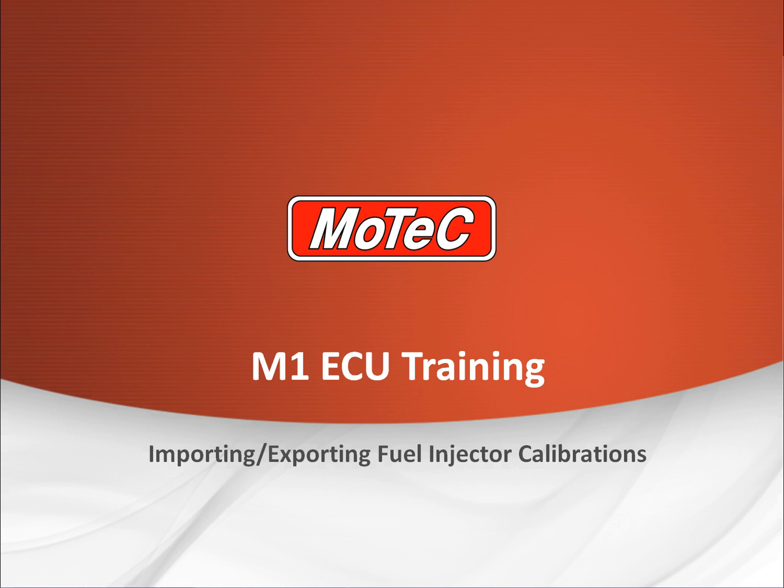Provided your existing setup has been correct, your engine displacement's correct, and all the original injectors have the correct information in for the file you've got, then importing the matching data for the injectors that you are fitting should give you a result where you shouldn't have to tune virtually any part of the map to get it right. In other words, if you get this process right, there'll be very little to do with the retune after the new injectors have been fitted. Right, so how do you do it?